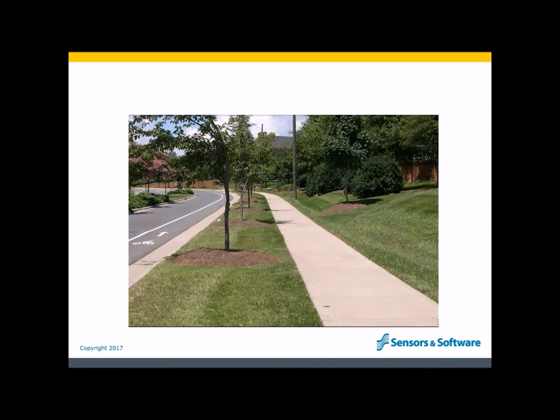In this photo, you see several different surface materials: grass, soil, concrete, asphalt. As GPR lines are collected across the different materials, expect the direct arrivals to change. So there is no possible interpretation error caused by the change in surface materials. I advise people to add a flag in the data as they go from one material to another. Or better yet, collect data with GPS so you can zoom in on these spots and see what was changing on the surface.